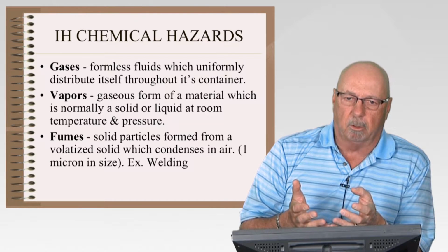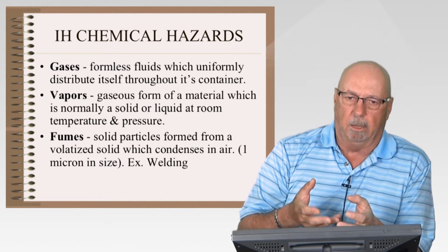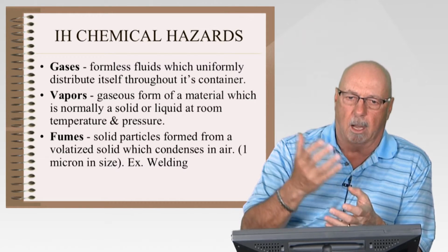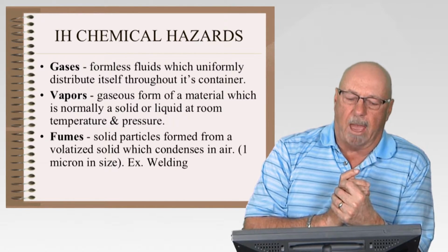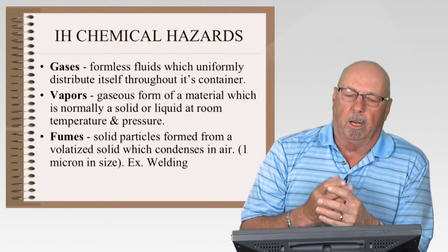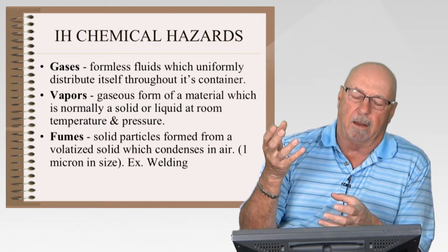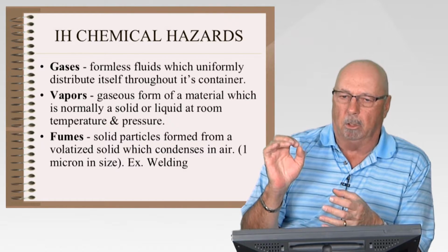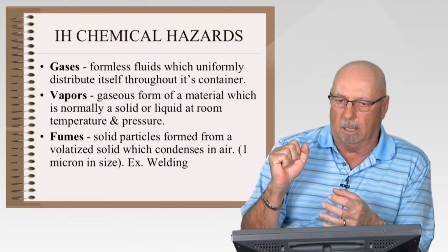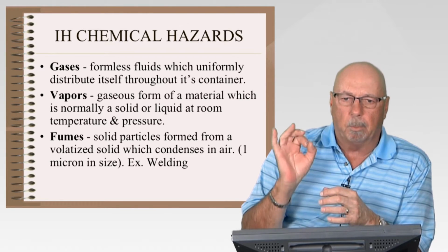As the temperature continues, that liquid would get hot enough that it would vaporize, or evaporate off that pool of melted metal. And when it evaporates, it hits the cool air, and that vapor molecule condenses within air and solidifies, and it forms a solid particle.